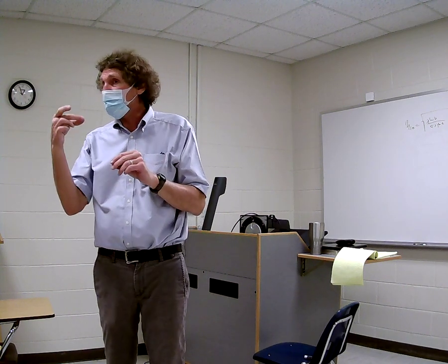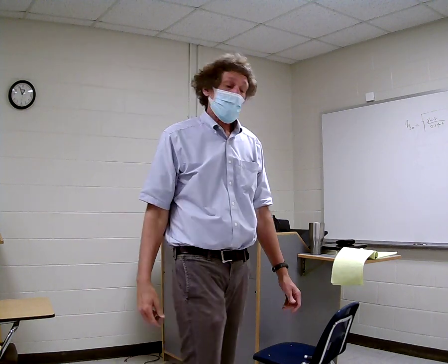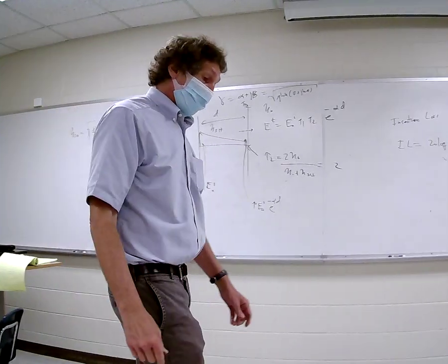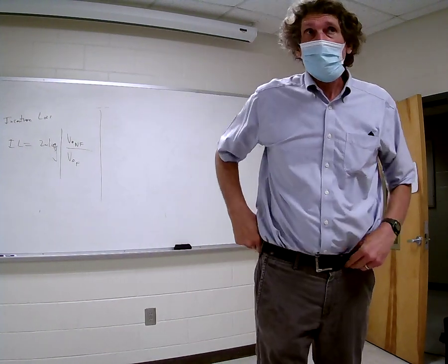You get them from things like ground loops or when lightning strikes. Now, when you get current in the same direction going to the input amplifiers and all that, it destroys them. Absolutely macerates them. And so, I've got to go through this with you. So we put a common mode choke on, and that will reduce it. It'll literally cause this huge impedance for common mode signals.